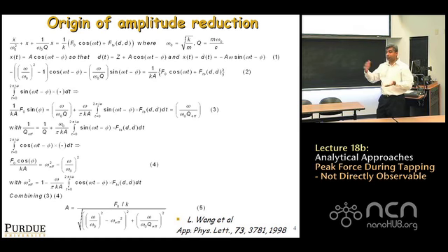So what this means is, Q tells you the Q factor of resonance, right? When you do a tuning curve, how sharp it is. That Q, if you think about it, is fundamentally a measure of how the energy of oscillation is dissipated in the surrounding medium, into hydrodynamics, into viscous drag in the surrounding. This other term in the integral is connected to energy dissipation at the tip sample interface. Okay?